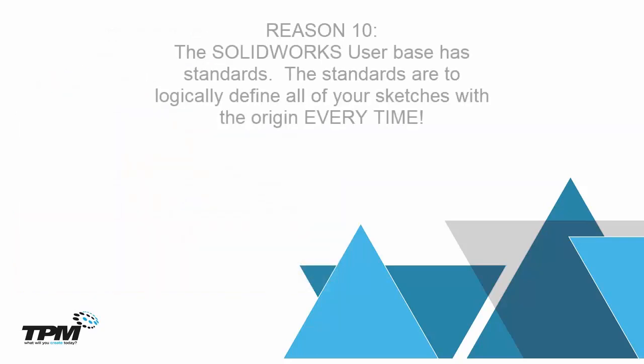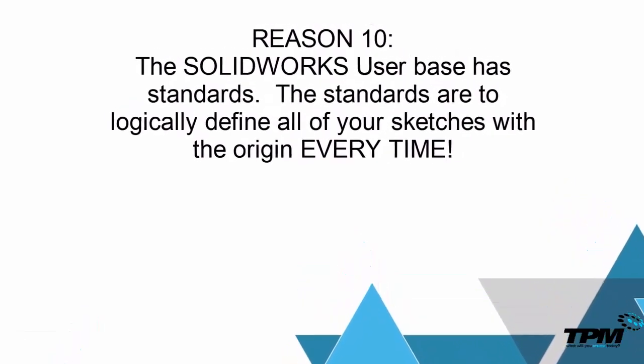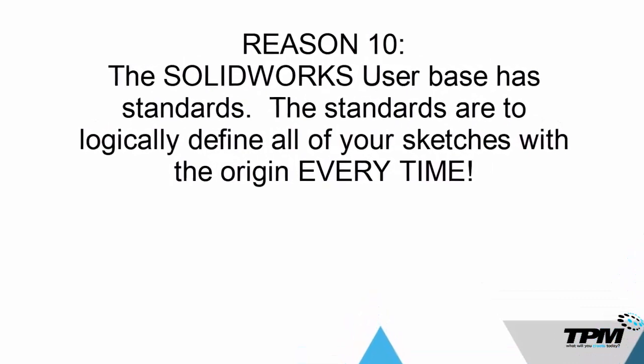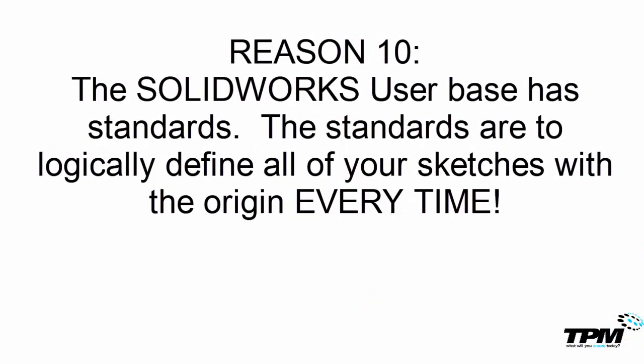Reason number 10, the SOLIDWORKS user base and the SOLIDWORKS community have decided that everyone should be logically defining all of their sketches, preferably with the origin somewhere in the middle so that we can all use our data together. So if everybody follows this standard, all of our parts will go together in assemblies, everything will make sense when we go to dimension and relate our parts, and everything will just be nicer for a multi-user environment.